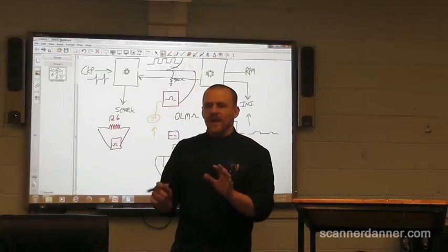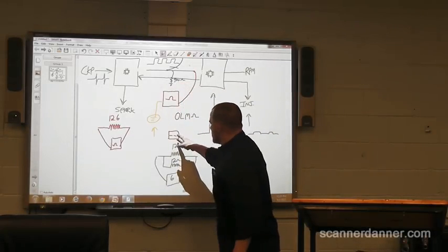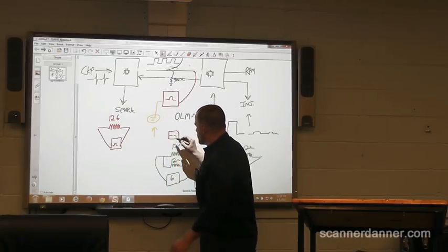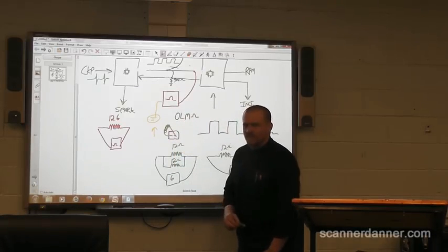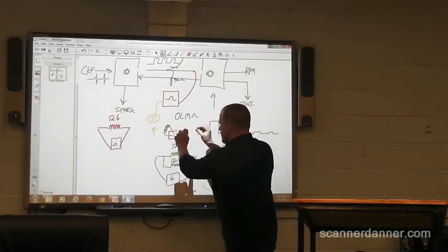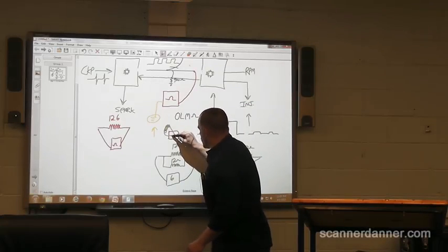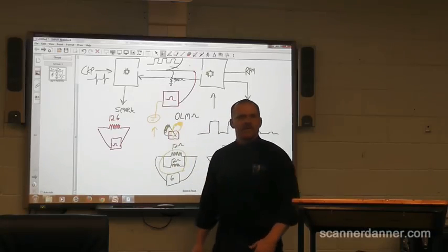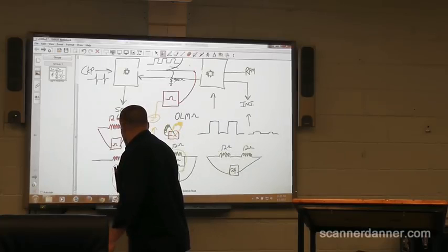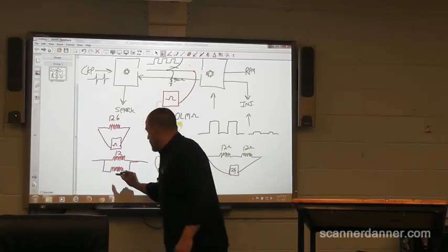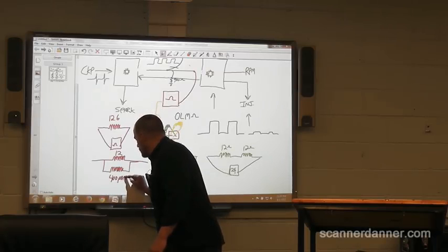So without going through all of that, here was my point. If I measure this injector that's 12 ohms, picture the coil, it's down inside of here. I can't draw three-dimensionally. That sucks really bad. And then you're holding your leads, and so your body is involved here too, and you've got resistance here too with your body. Don't you have this going on? You do. However, let's do the math on this one. We're going to need a calculator. 12, we'll just use 12, okay? 12 and 400,000.